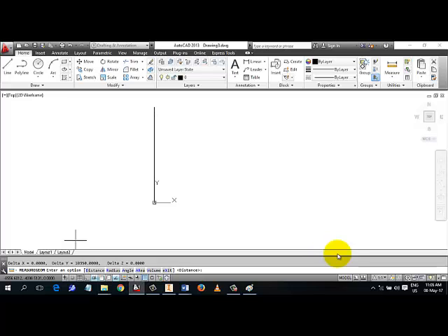Is that okay? So in the gray section, what do we have there? Delta X, 0, delta Y, 10,350.0000. It is telling us that the length of this line along the X is 0. But along Y axis is what? 10,350. Along Z axis is 0. So it's a one directional line. But you can have a two-dimensional line or 3D, a line in 3D space.